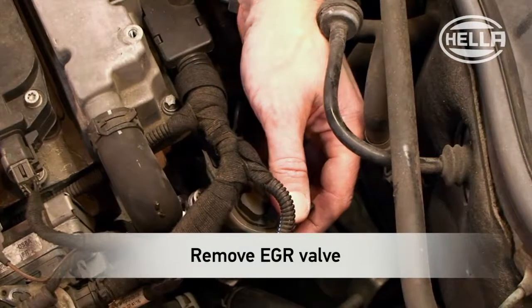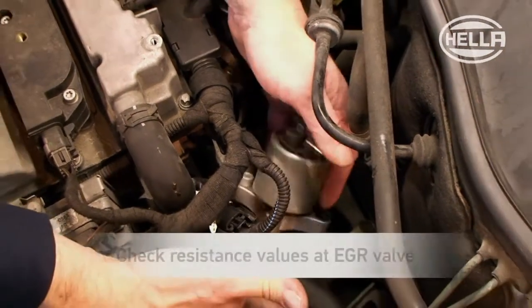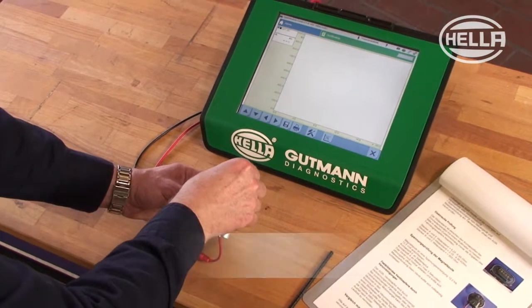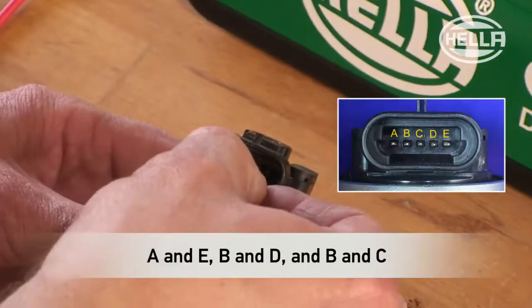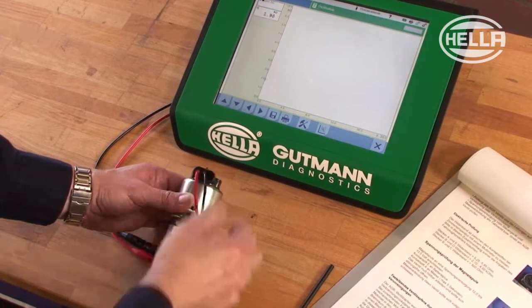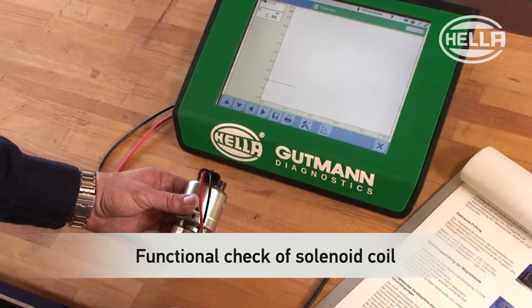The EGR is removed for the rest of the tests. Now, perform an electrical check to determine the resistance values of the EGR valve based on the vehicle manufacturer's specifications. The resistance must be measured in turns between contact pins A and E, B and D, and B and C at room temperature using an ohm meter. This is followed by a functional check of the solenoid coil.